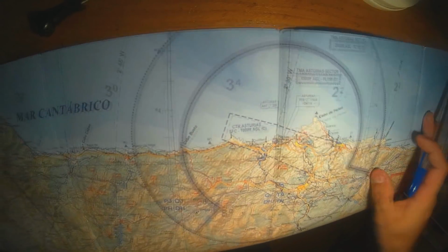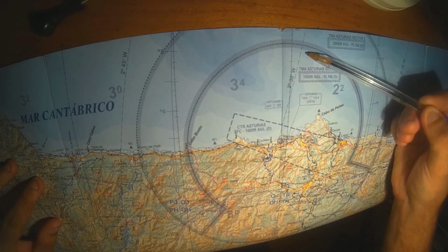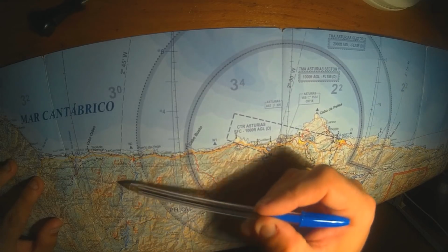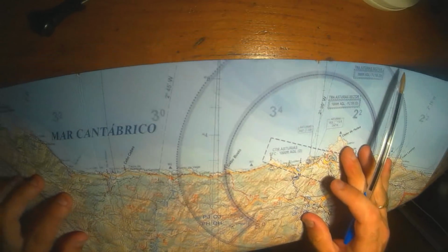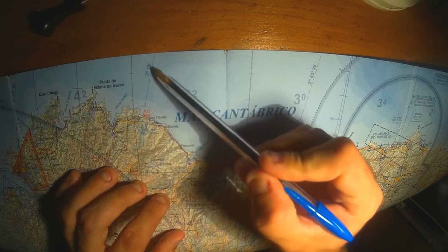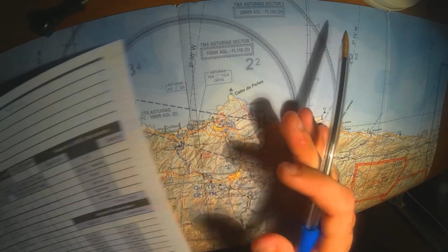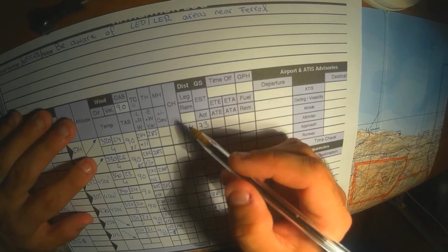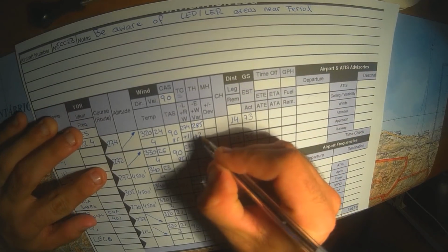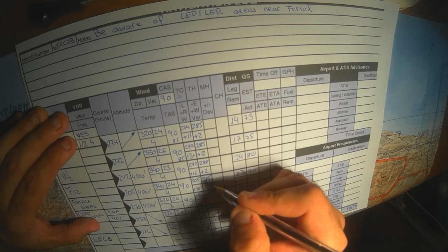Variation is known as the angle between magnetic north and true north. Variation lines, also known as isogonic lines, are represented in maps with dashed lines and a number of degrees, west or east. If we are west, we will add the number of degrees to our true heading, as is our case. If we are east, we will subtract the number of degrees from our true heading. Most of Spain is over the 2 west isogonic line, but west-northwest of the peninsula has a change to 3 west, so we'll take both corrections for our flight today.